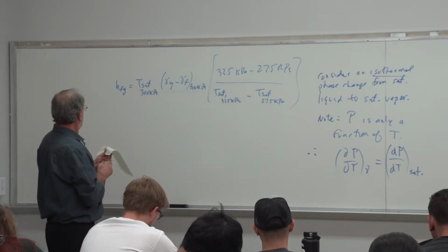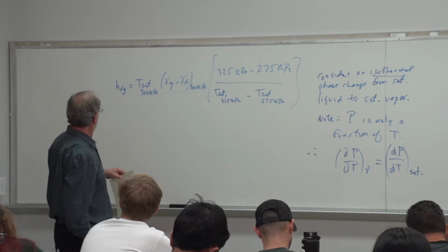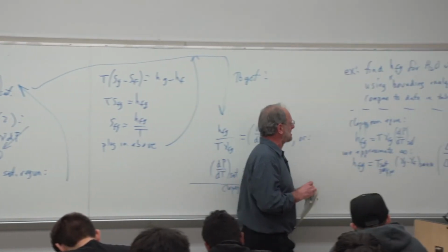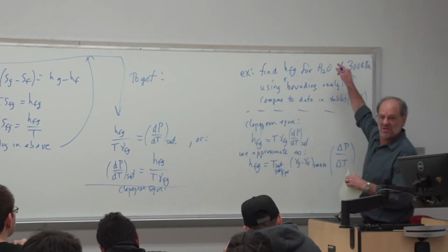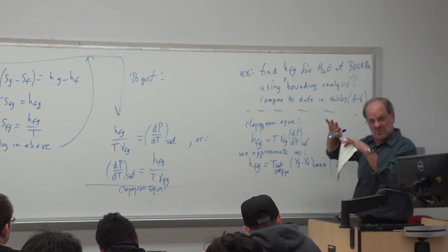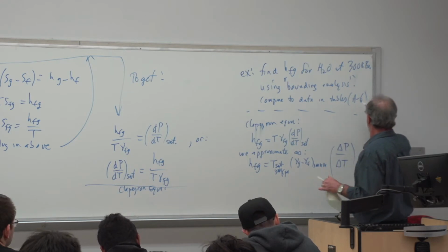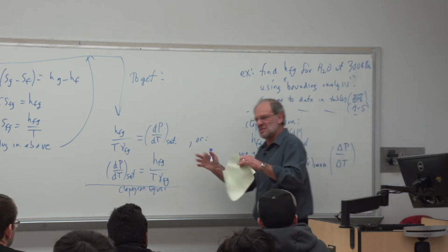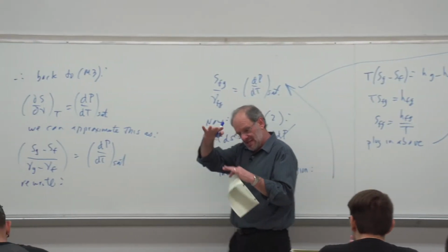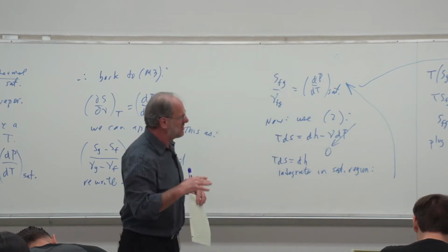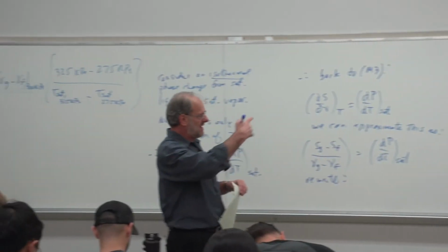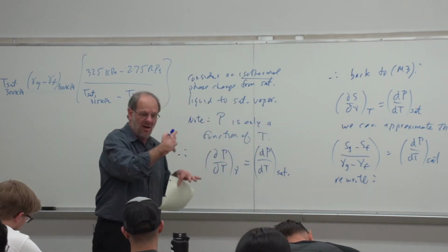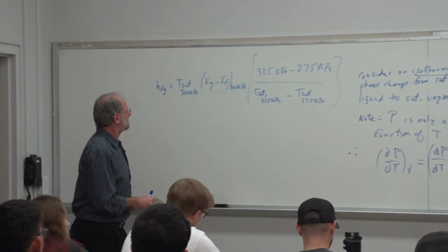And as I'm saying all this, I realize I've made a little mistake in my wording. This is all in the saturation region, so I don't know why I'm thinking table A6. Table A5 is our pressure table that corresponds to the saturation region. So this needs to say A5. Okay, and then I mentioned the subtables in table A6. That's not applicable here. We're just looking at table A5. It lists our data in increasing order of pressure. So we've got data at 325. We've got data at 275. We've got those as the bound around 300. So that's what really should be said here.